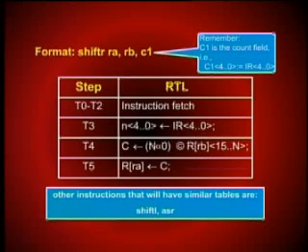So as a result, we need to feed zeros on the leftmost bits, and that is indicated, 0 is replicated capital N times, and this is concatenated with the shifted bits, which are actually 16 minus capital N. So as an example, if the number of shifts were 2, we will shift by 2 positions and we will have 14 original bits. 2 bits would be lost, and on the left side we feed 2 zeros into that particular register. And after concatenation, as a result, we will have in buffer register C the original 14 bits shifted by 2 positions, and on the leftmost 2 zeros.